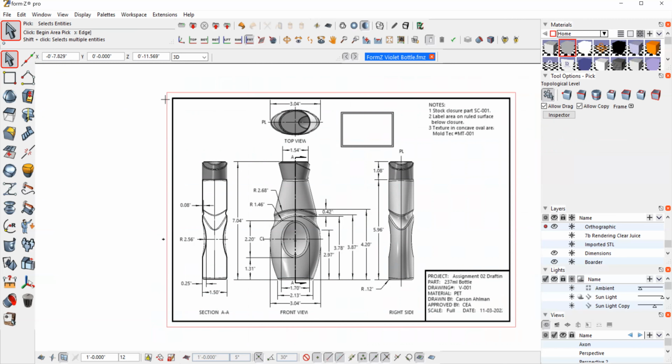The reason we have borders on engineering drawings is because we want to communicate that this is the entire drawing. When there's a border, an engineer looks at it and goes, okay, this is the entire drawing, and here's the title block with the specific information. Because quite often people will crop out and only print sections of a drawing. Like I might do the front view of this drawing because it talks about certain dimensions or the cross section. And I might send that to an engineer and say, here's a detail. That engineer can look at that and go, he doesn't see the border, he doesn't see a title block, so he knows this is only a fractional part of a complete drawing. It's just a way of communicating that we have our entire drawing connected here.